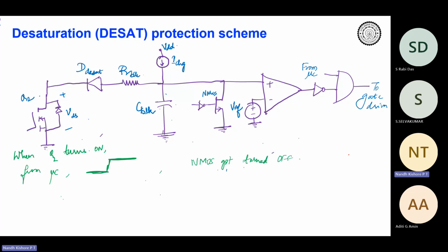This happens instantaneously. You understand that it's a signal level MOSFET, so it can turn on and turn off very fast. But how would it come to Q2? If you see the realization of the circuitry before the gate part, we have a gate driver over here.